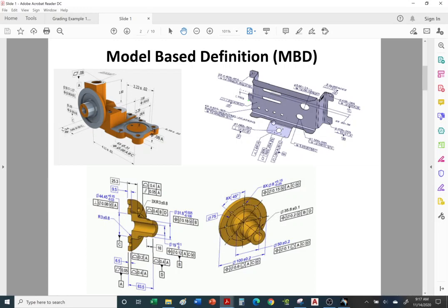Okay, so if this is 1 inch, I can be off by plus 0.030. So this can be as long as 1.030. And it can be as low as 0.970, which is just 1 inch minus 0.030. So once again, the dimension is 1 inch plus or minus 0.030, or also known as 30 thousandths of an inch.